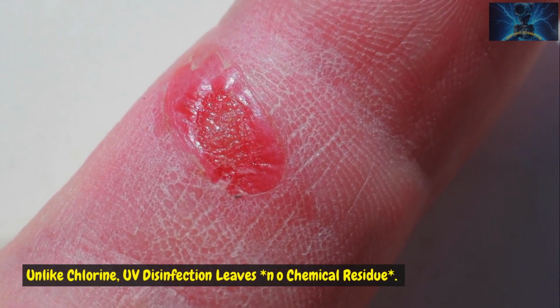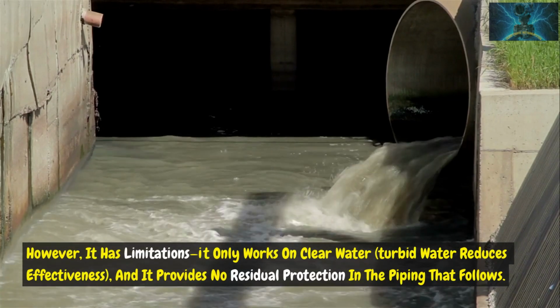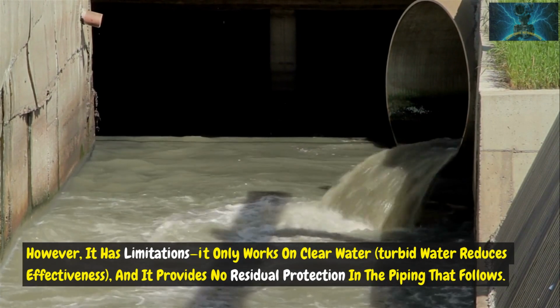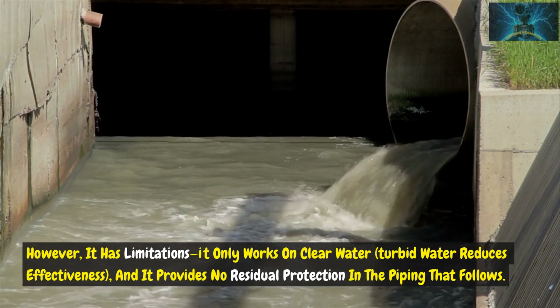Unlike chlorine, UV disinfection leaves no chemical residue. However, it has limitations. It only works on clear water. Turbid water reduces effectiveness, and it provides no residual protection in the piping that follows.